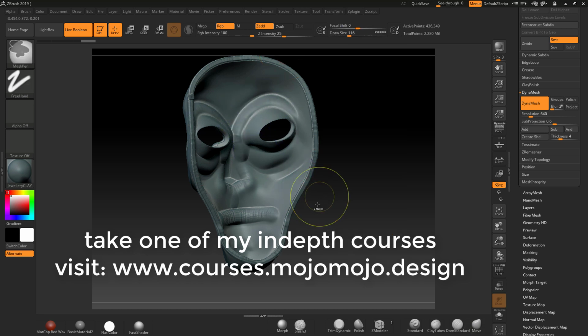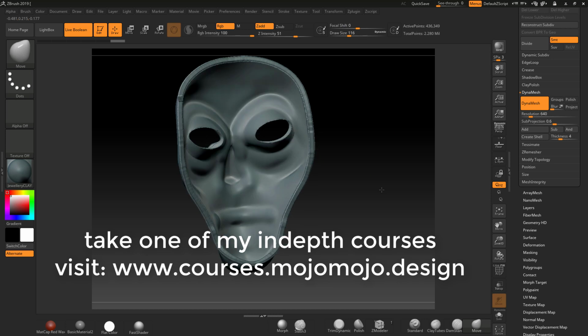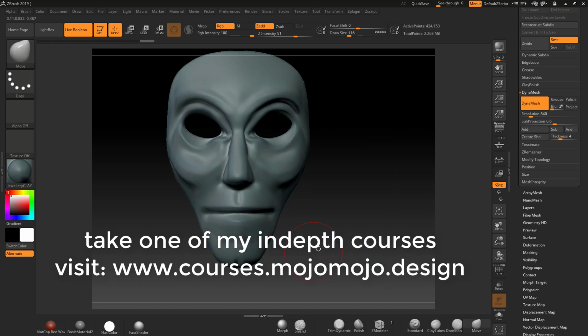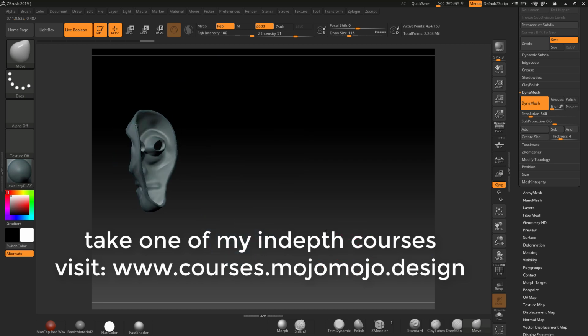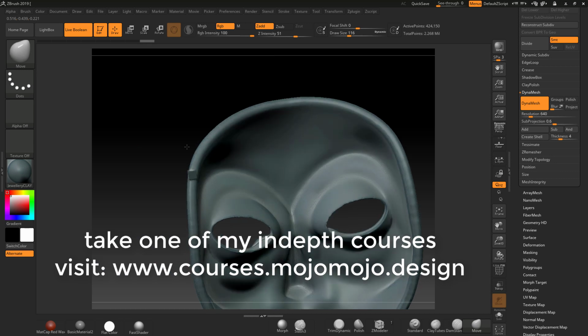clean that inside. By the way, it's a polygroup, so you could press Control Shift on here just to isolate the inside so that you're not affecting the outside of the model at all. And you can come along here, clean all this inside up, press Control Shift to move outside of that, and then of course clean up the edges where you need to. And when you're finished with that, you can just re-Dynamesh it. And that then gives you that mask as well. The inside at 2 millimeters as indicated by the cube.